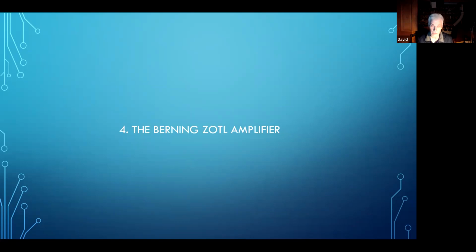My idea behind this was to circulate the full current all the time. So you stayed away from crossover notch problems, crossover distortion, things like that, because you'd be circulating the full current all the time, but you'd be returning it to the power supply continuously, so it wasn't dissipating a lot of heat.